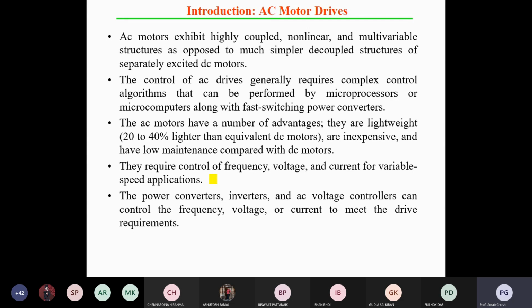That control signal will be compared as per your logic. If it is an inverter, what types of modulation are there? There is a carrier frequency and the modulating frequency as per the logic. So from that control signal you can generate the pulse width, or the pulse sequence of the inverter. That pulse sequence is fed to the inverter switches, as per the changing of your motor load.